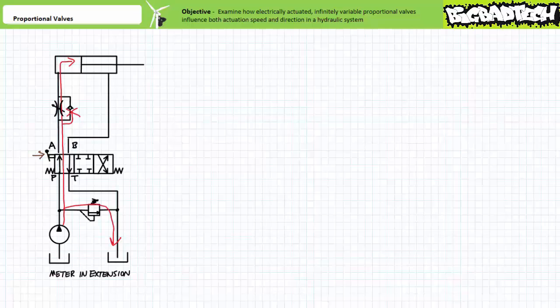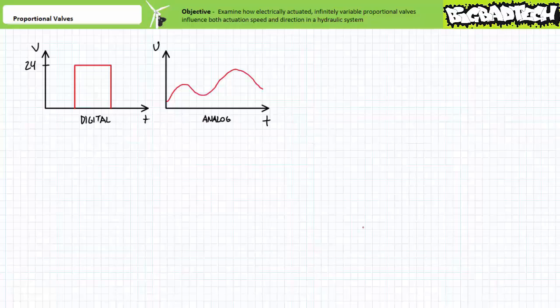The directional control valve, being solely an on or off switching device, can induce pressure shocks as passages are selectively fully opened or fully closed. Proportional valves, in contrast to a regular solenoid-operated directional control valve, are electrically actuated valves that make use of an analog rather than a digital input signal. Analog means continuously variant within a given range. Digital or discrete, in contrast, means fully off or fully on with no intermediary value. A traditional solenoid-actuated directional control valve is digital in nature.